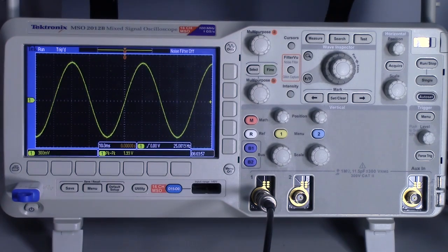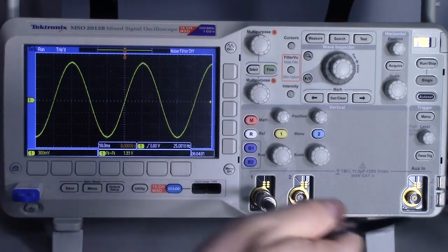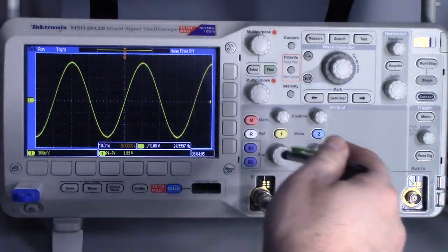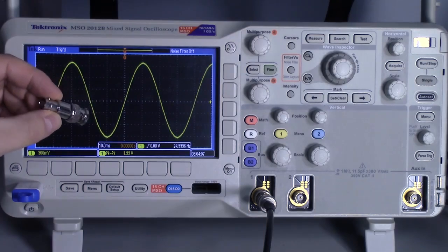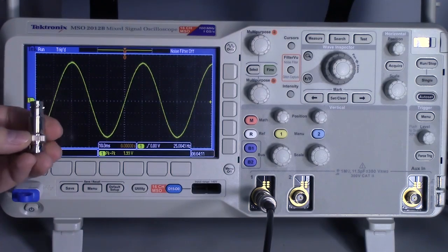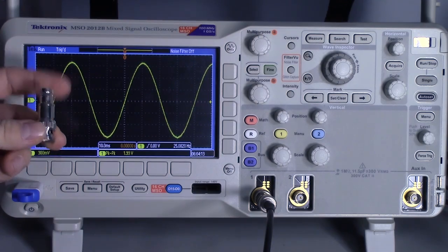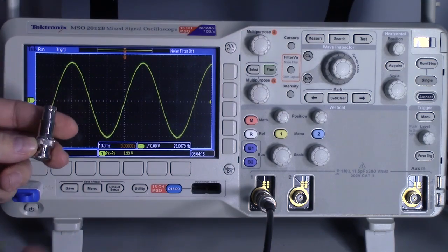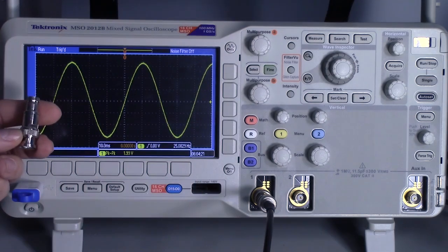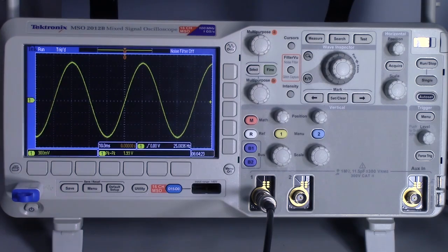Now, right now I've got, off screen, a coaxial cable, which is right here. I have it connected directly from a function generator, and I'm using one of these pass-through terminations. The source of the function generator is 50 ohms, so this is also a 50 ohm termination, but it will pass the signal through. That way what is being sent from the function generator is actually what we see. And I'll have another video a little bit more in depth on that as well.